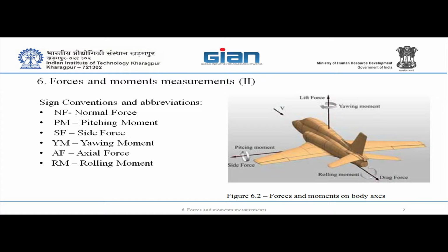The aircraft is flying forward, and no doubt, normal force will be vertical to the body axis. Normal force, no problem, it will be upward. Pitching moment, if you're flying forward, whatever will pitch you nose up, nose up. So the rolling arrow is showing well, but the right-hand direction shows badly, you see, because if you are rolling up, your axis should show the right way, and this one is showing the left way. So be careful.